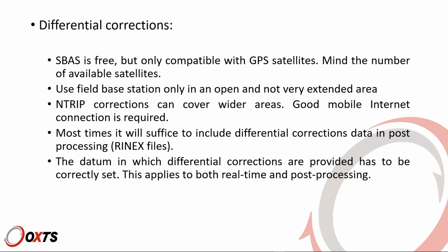Most times it can be enough to apply differential corrections just in post-processing through RINEX files. The advantage is that you have no interruptions in the flow, in the stream of corrections. And so you can post-process the data with RINEX files to improve that accuracy. Regardless of the way you apply corrections, using NTRIP or a field base station or RINEX, the datum in which diff corrections are applied needs to be specified.